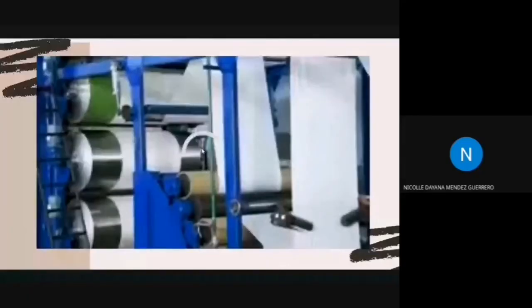In general, the dryers rotate through the use of gears. The hollow rollers are internally heated by steam. The heat is transferred to the wall of the roller and to the surface, which by contact with the paper or fabric will increase its temperature and eliminate almost all the water.